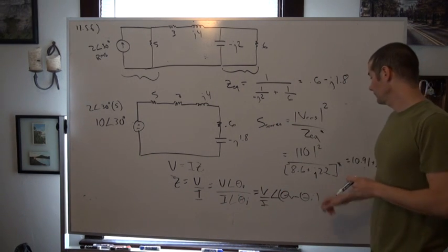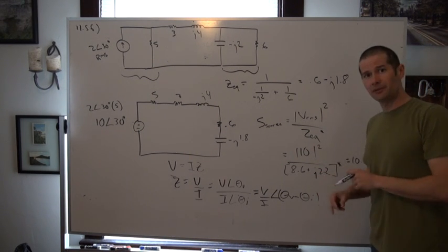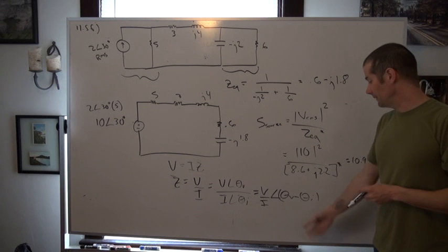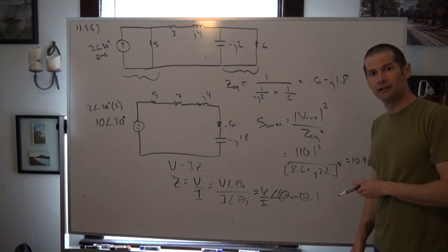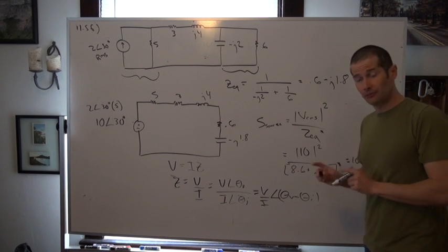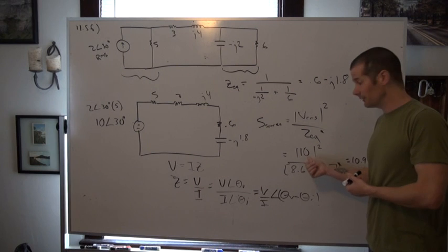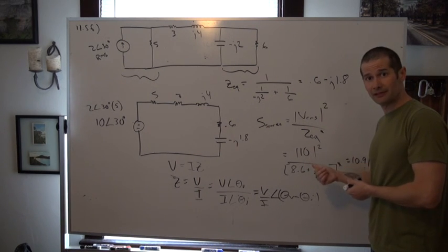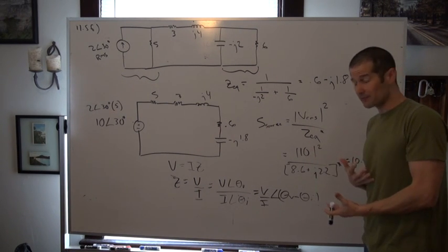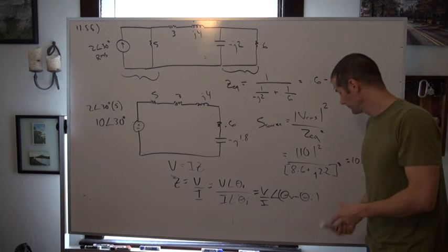In this case, here if we did not conjugate that in the denominator, then we would actually not come out with theta V minus theta I. So we have to conjugate that. But it's important to remember here, guys, it's pretty cool that we don't need the phase angle right up here when we square that magnitude, because the phase angle of the complex power is already right here once we conjugate that and then divide through.